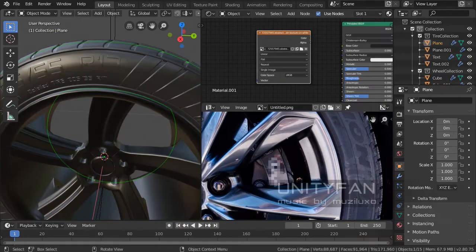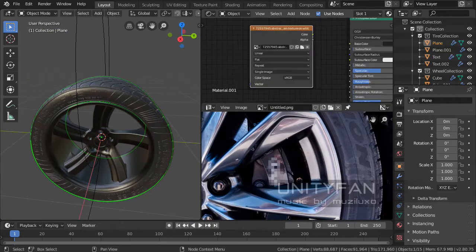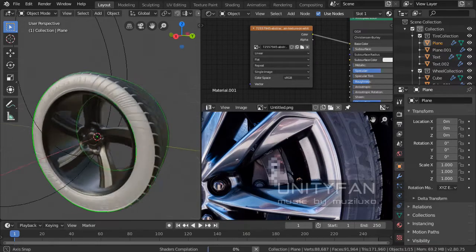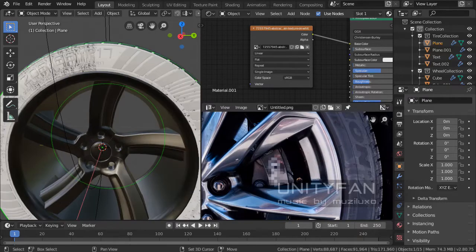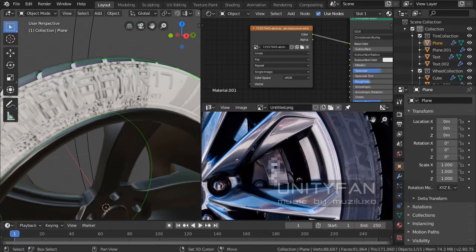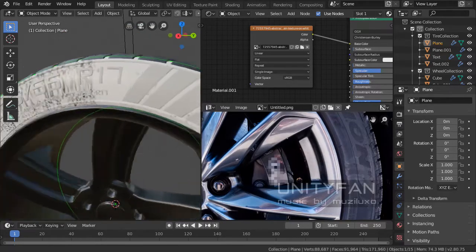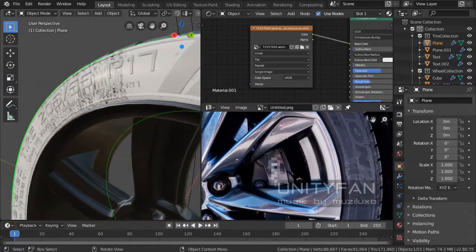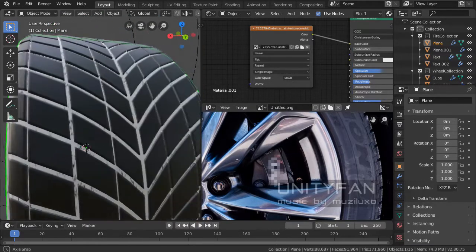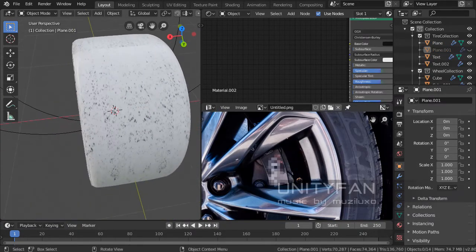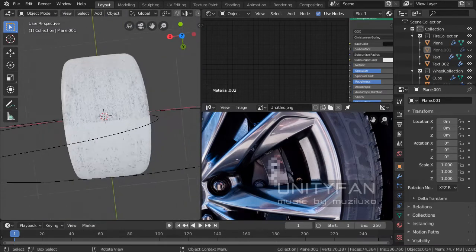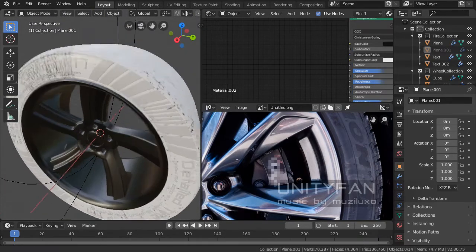Also I have to say the geometry has to be prepared in a certain way too, because it has to be unwrapped. With unprepared geometry, we get issues like this, where the texture is stretching and laying on the geometry incorrectly, with steps and stretching in a weird way.